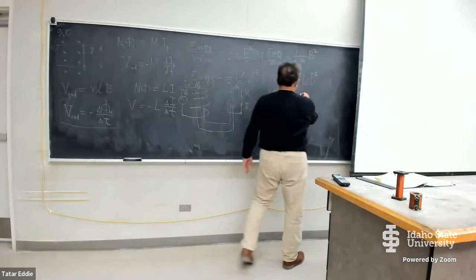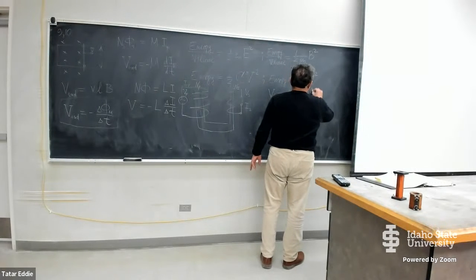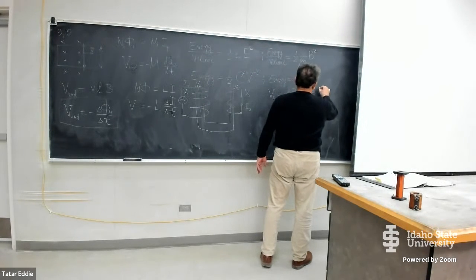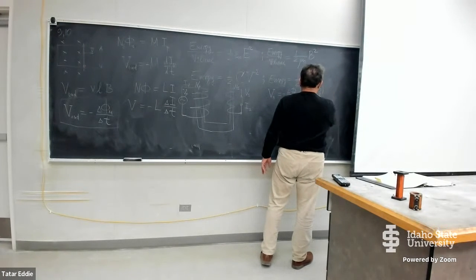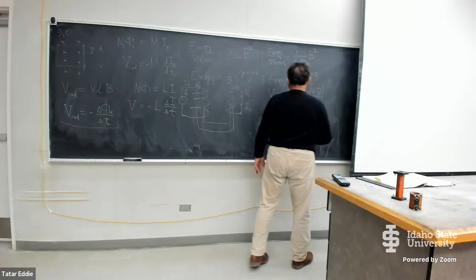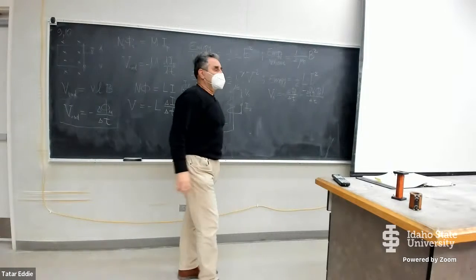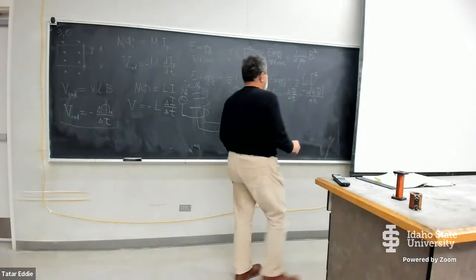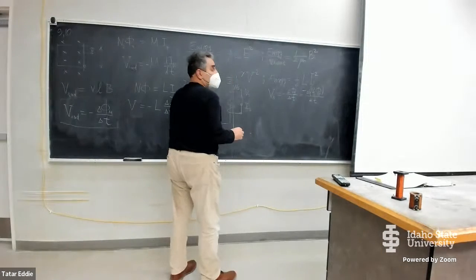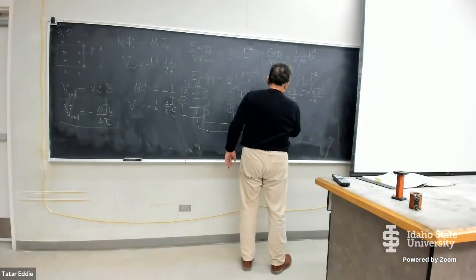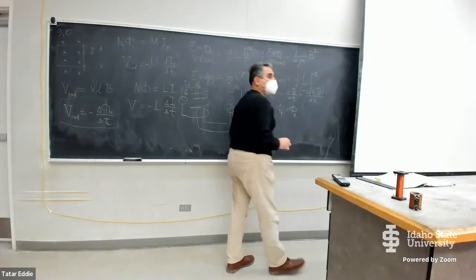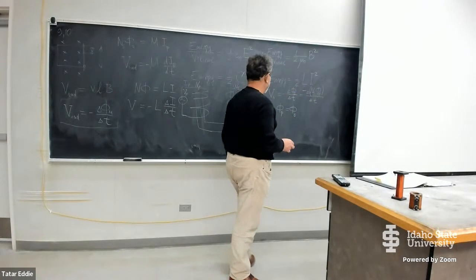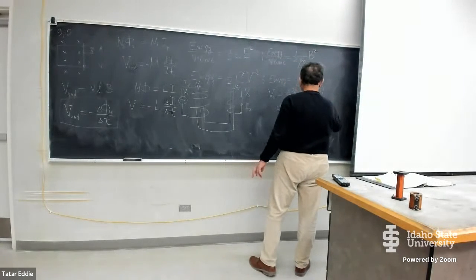But the magnetic flux to the secondary is the number of turns in the secondary times the magnetic flux for one turn, like this. And there is a minus sign again, that doesn't do much. But now look, this iron core makes sure that whatever magnetic field is created in the primary, that magnetic field with practically no losses reaches the secondary.